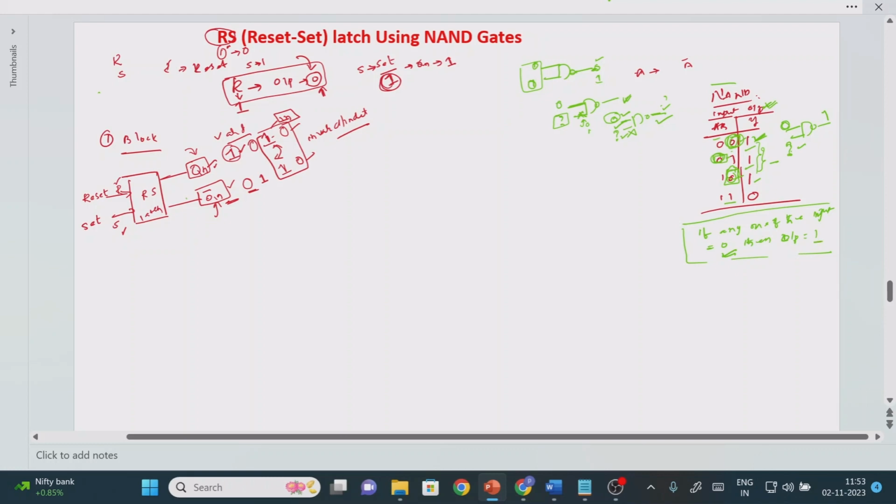Now you might have the doubt: if any one of the input terminal values equals 1, can I find out the output or not? For example, let us check. What is the input value? This one is 1. What is this value? Unknown value. What is the possibility? Either it may be 0 or 1. For the first time we will consider the input value equal to 0. So 1 0, what is the output according to the truth table? 1 0 means 1. So this is fine. Next, what is the next possibility?